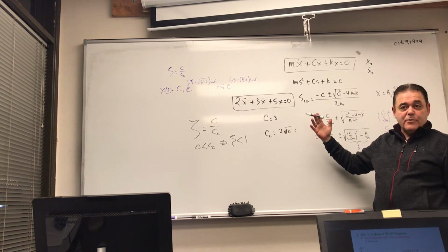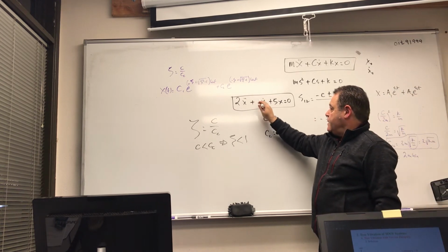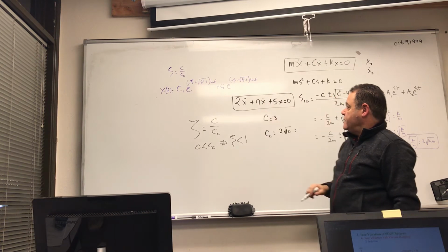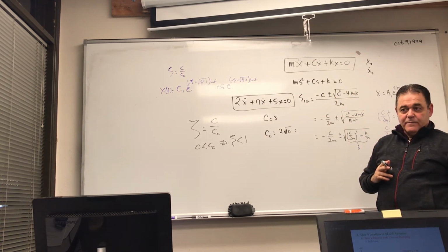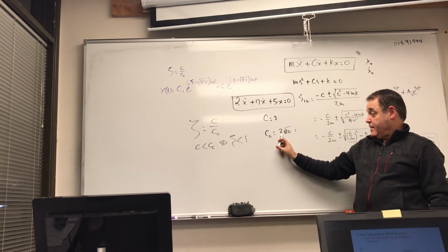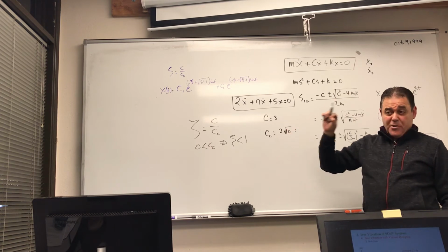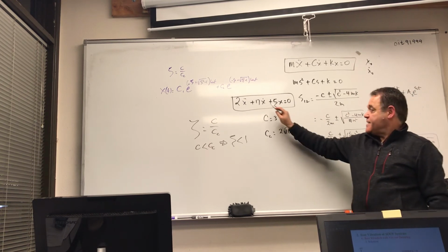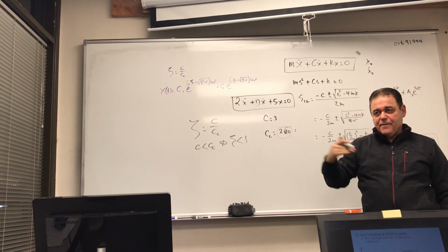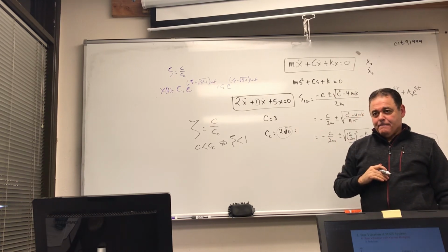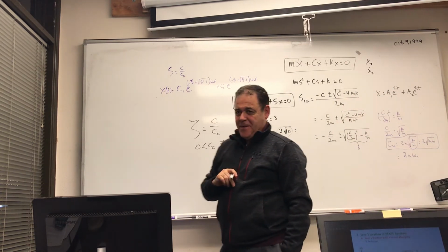I could do that on the test. Now, if I were to have this one as 17, it would be over damped, right? But I can design it so that it will be critically damped, in which case this value had better be equal to exactly this. As the designer, you have the control. What does it mean when it's critically damped? C is equal to CC.